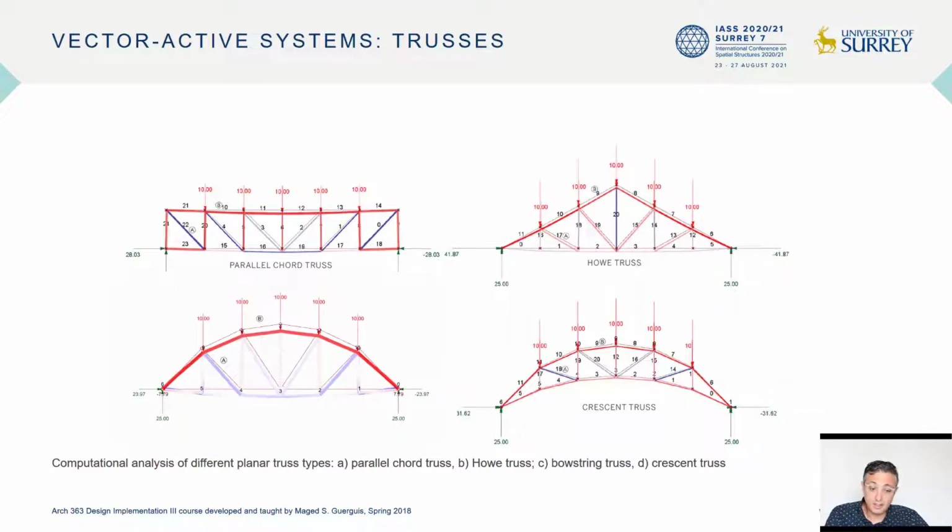Starting the investigation of long-span structure systems, this exercise explored the analysis of planar trusses, constructing and comparing multiple types of truss models. This exercise focused on identifying areas of compression and tension, which helps the students evaluate the mass, displacement, and the stress. Students were able to associate the impact of topology and of the members' arrangement on the truss strength and performance.